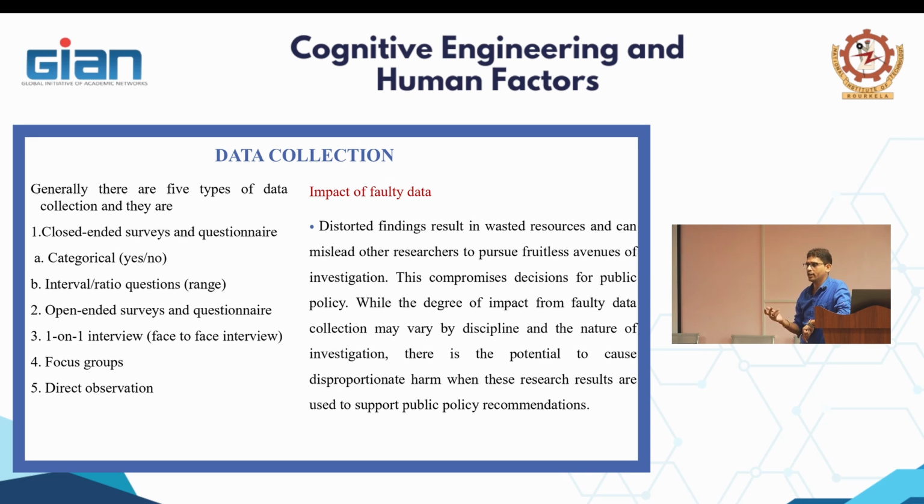You said, okay, I have less time, I will only measure 50% of them, and 50% is sufficient data, I will design based on that. But the population size was given to you and you had to design with respect to the maximum, but you designed with the minimum. Then when the actual time of use comes, the tallest people are not able to come in or go out, and the design will fail.